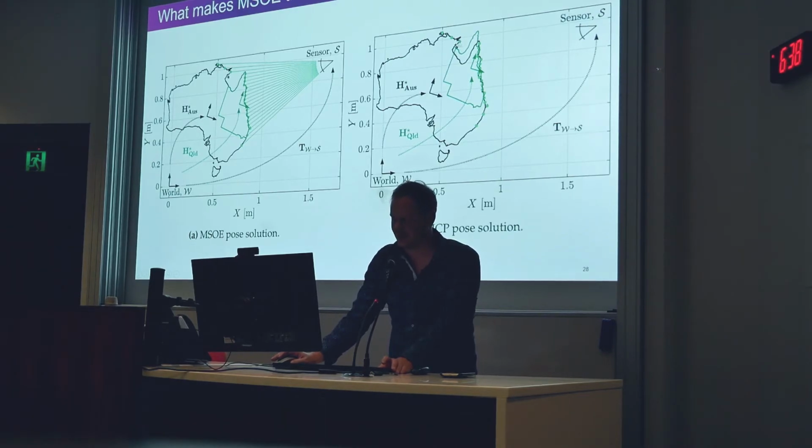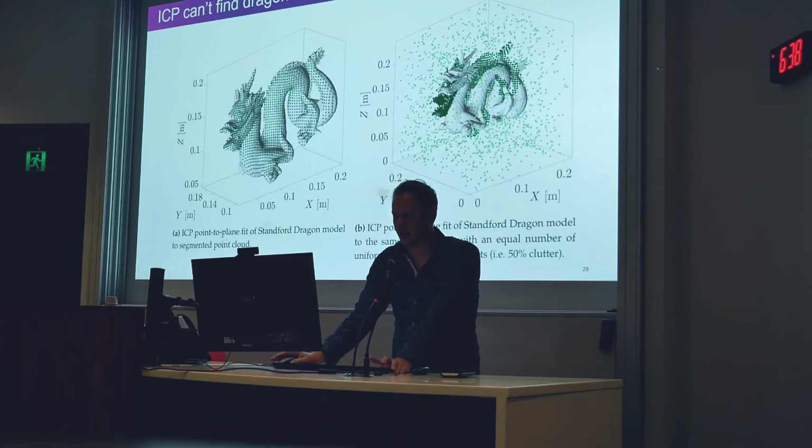And it's wrong because it didn't segment out these three measurements here in the Northern Territory, and there's one measurement down there in Sydney. So it's tried to fit this geometry model to all of the Australia point cloud, and its best fit to minimise the error was to bring it a little bit closer to these three. So you can see why it hasn't worked.